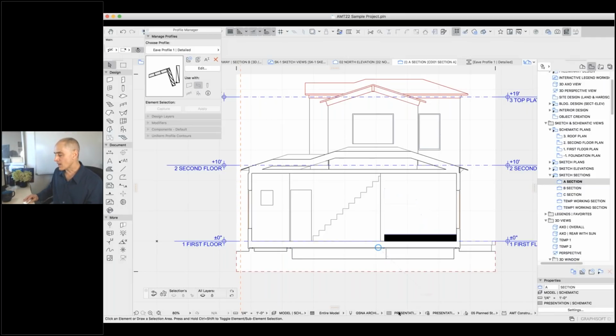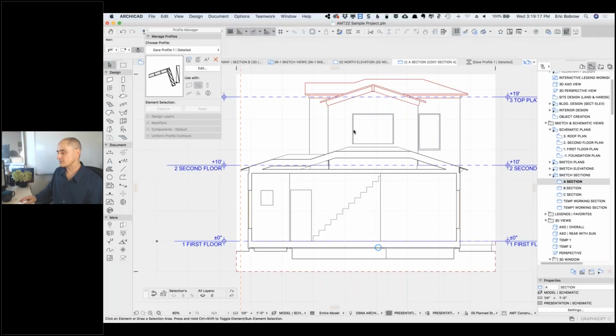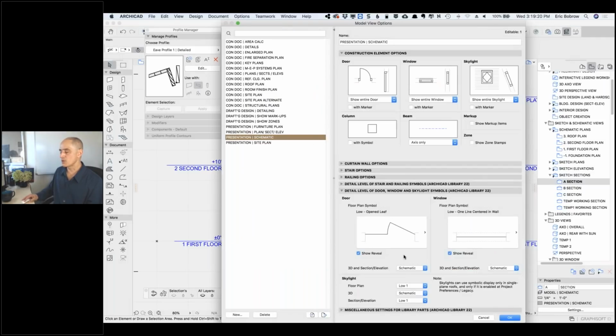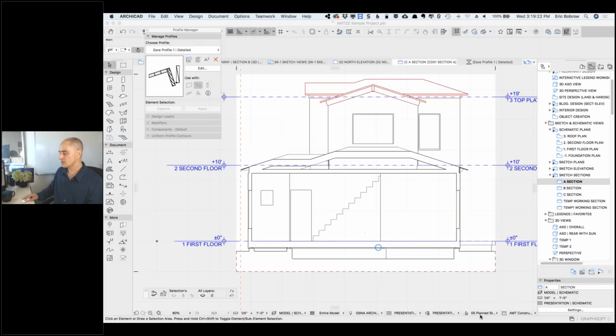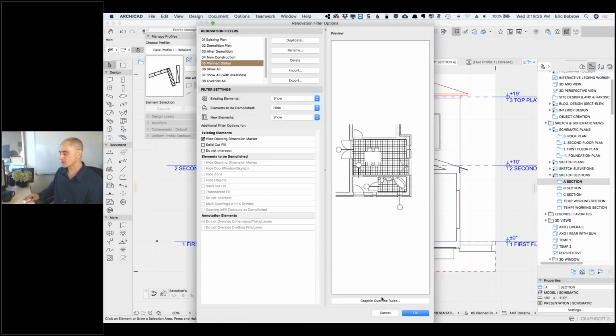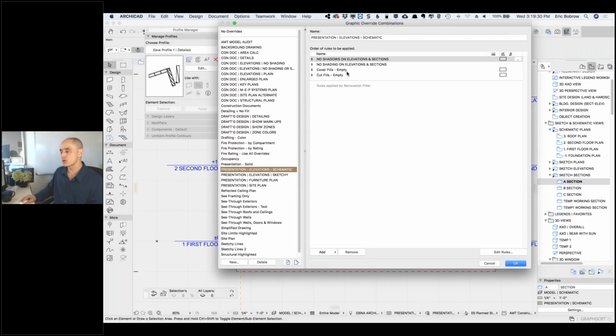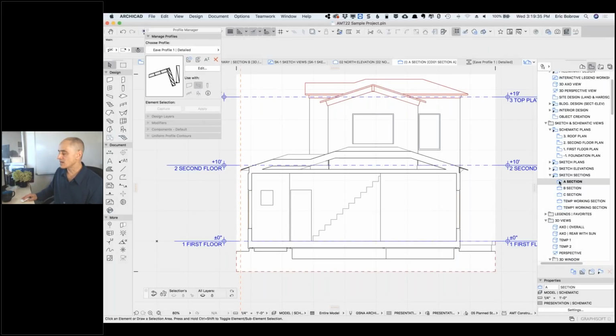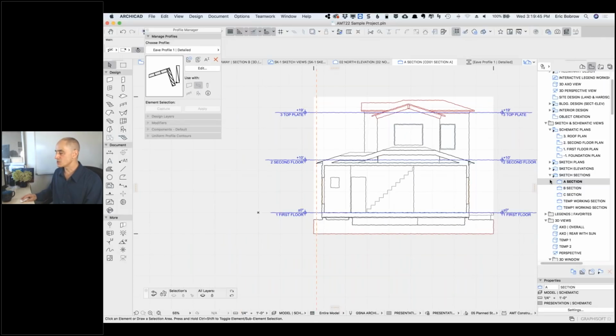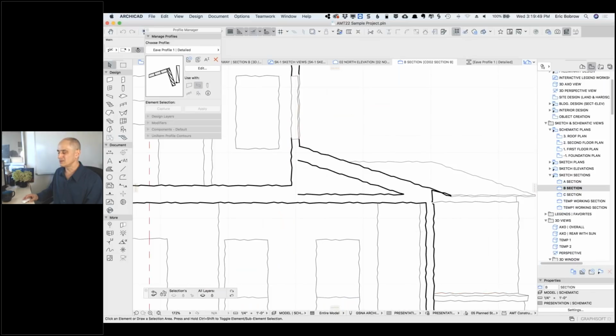And then I also had the model view options, in this case, saying, show these things very simple, and the graphic overrides. I said, turn off the shadows and shading, make everything white, etc. So that's the combination. And in this case, if I do it with the sketchy settings, from a distance, if you did a screenshot, this communicates pretty well. If you zoom in on it, you may say, ooh, look at that.